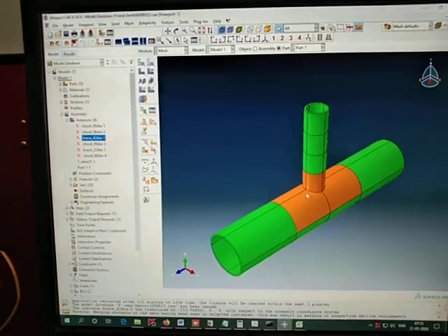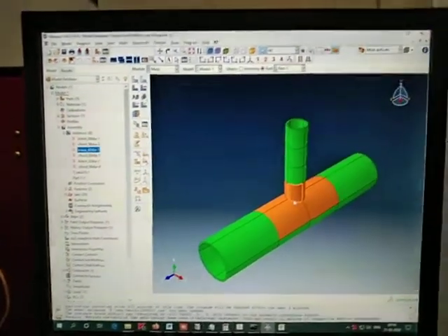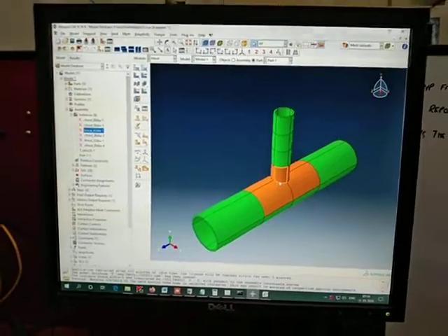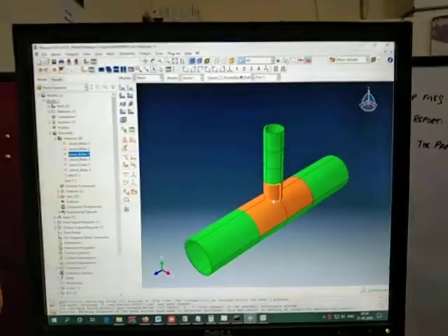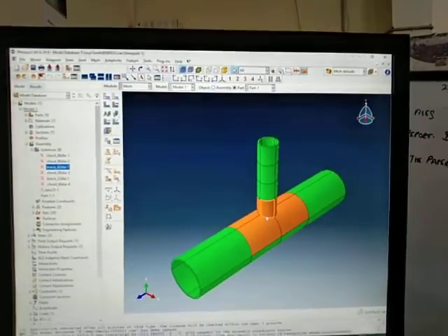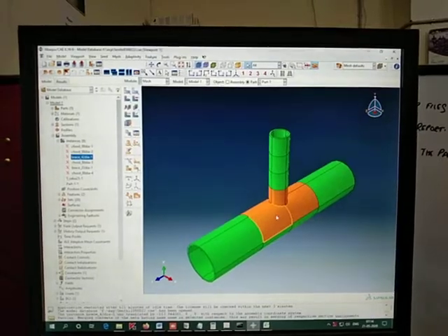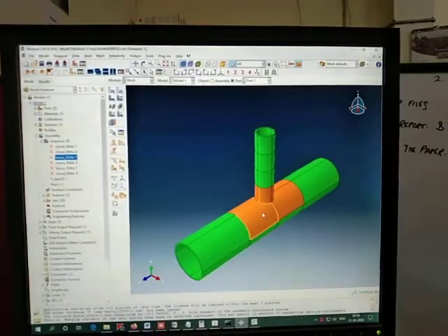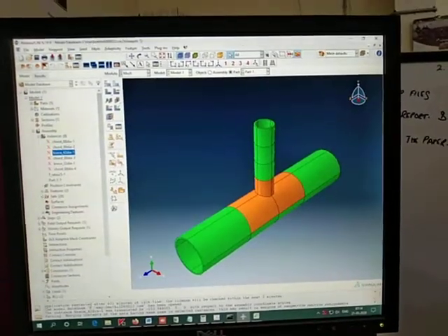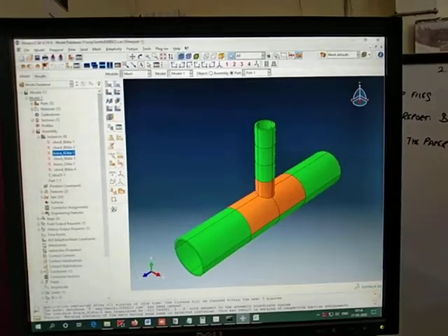One more important thing is, if the object is highlighted in green or yellow: if it is green it can be meshed with structured mesh, while if it is yellow it will be a sweep mesh. It has two varieties, medial axis and other options, but if it is brown, it cannot be meshed with these regular mesh types. It needs a bottom-up mesh or similar. To avoid that, we need to partition each and every part. So here plays the crucial part of partitioning.